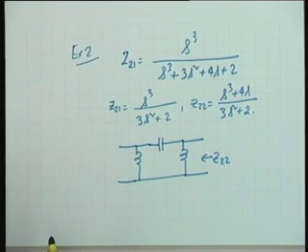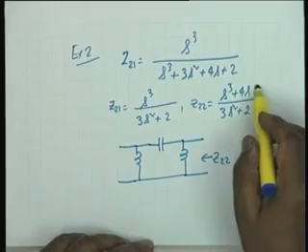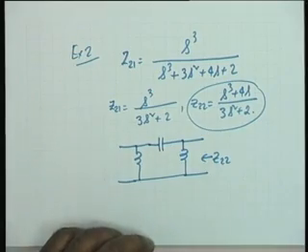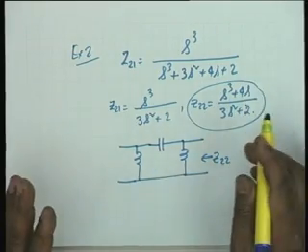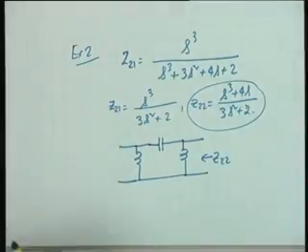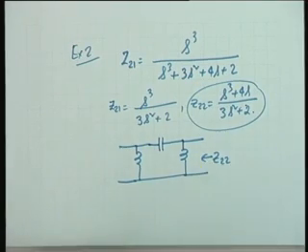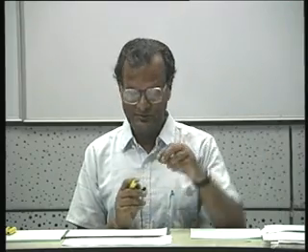So you said the transmission zeros of Z22 should be the transmission zeros of Z21. No, no. There is no transmission zero of Z22. Z22 is a driving point function. You have to develop Z22 in such a manner that the zeros of Z21 are realized. Zeros of Z21 are the same as transmission zeros. If it was S square, pardon me, if it was S squared, then 2 zeros at the origin and 1 at infinity. We will do that example also. In fact, we will do S to the 4th also. All right.